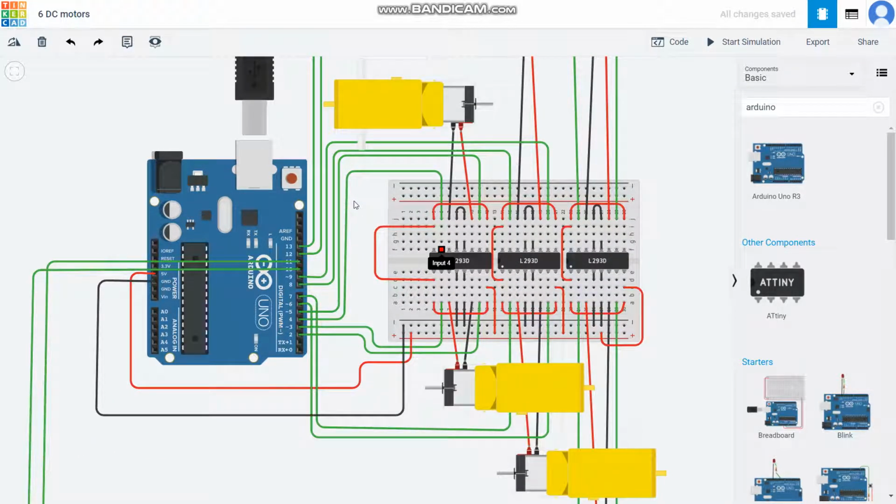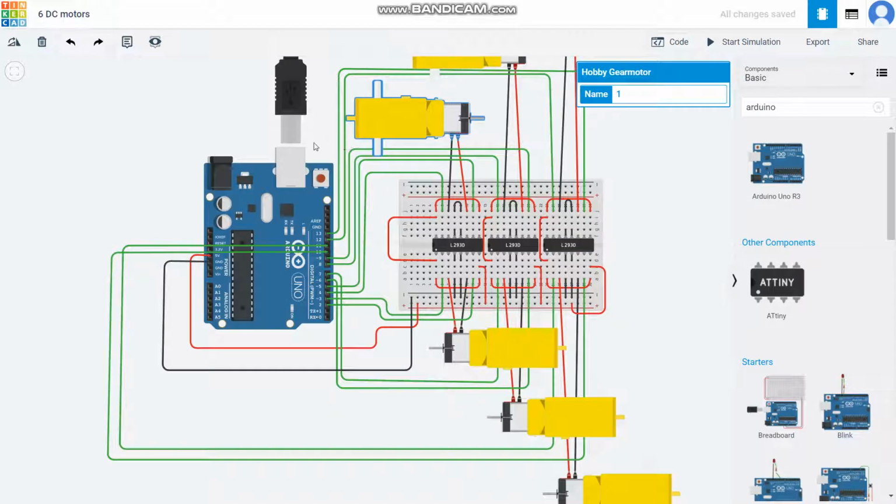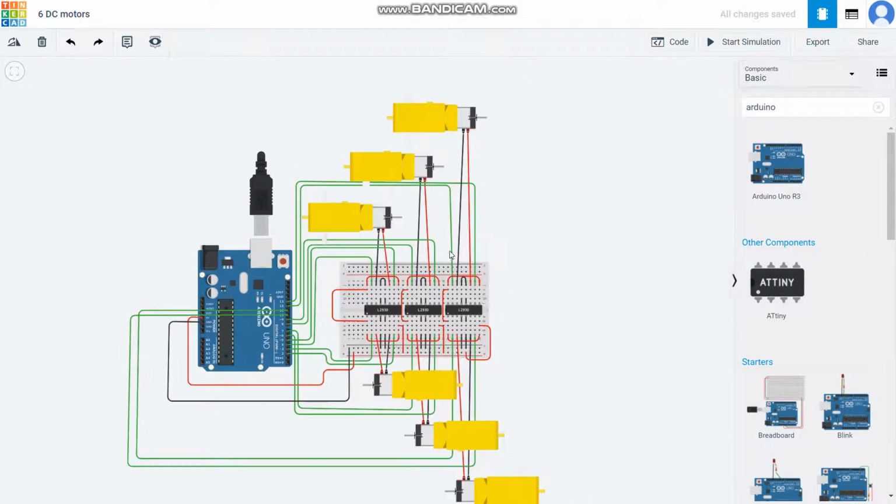Make sure that you check all the points here in the H-bridge motor driver to avoid confusion. The first gear motor is connected to pins 4 and 5, while the second gear motor is connected to pins 3 and 2. This input dictates a current flow in the motor, which is the output of the diagram.